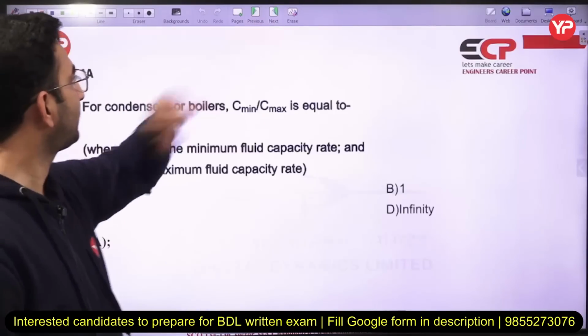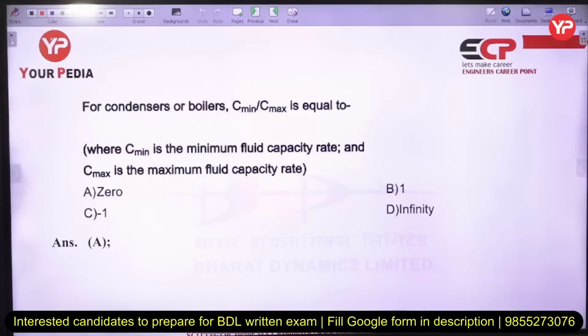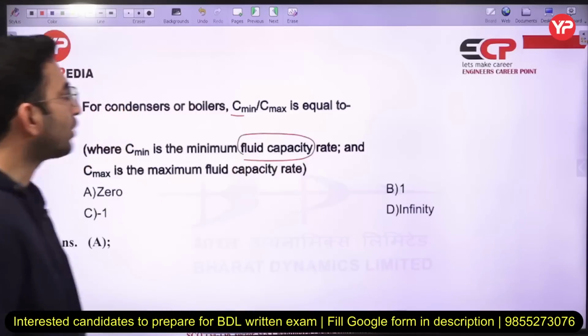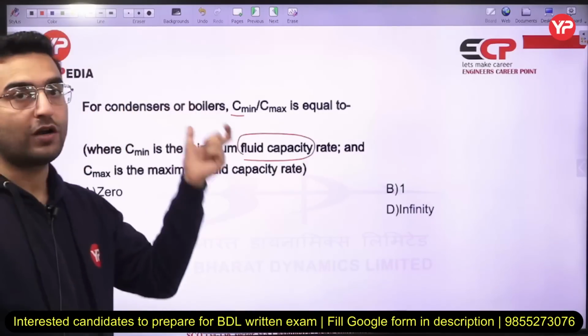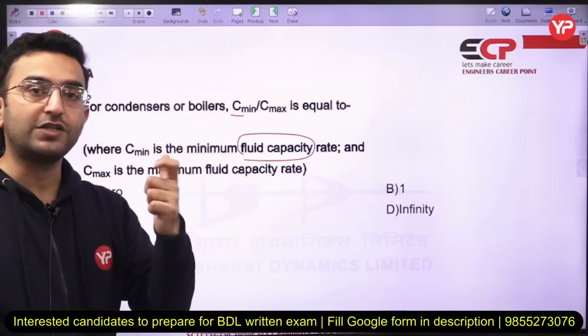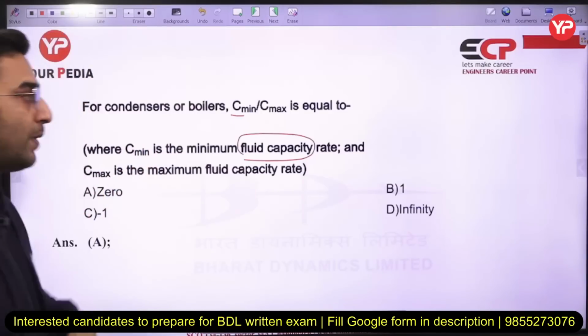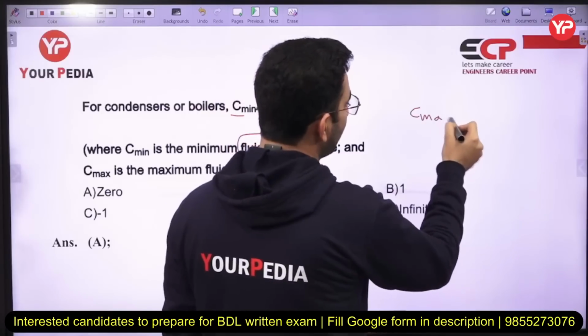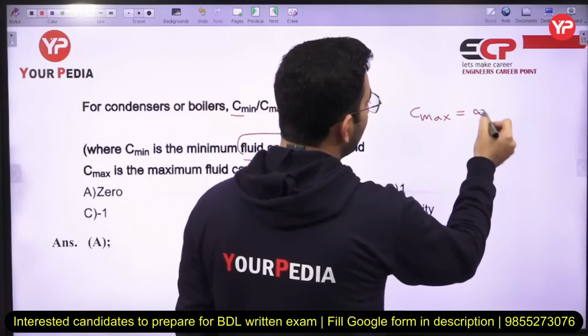Next part, for a condenser or a boiler, the ratio of C min by C max, where again the C is representing the fluid heat capacity here. So if you see in the case of a condenser or a boiler, one fluid is having a phase change here. So whenever there is a fluid phase change taking place in a heat exchanger, you always have to remember the value of the maximum heat capacity. The value of the maximum heat capacity can become equal to infinity here.